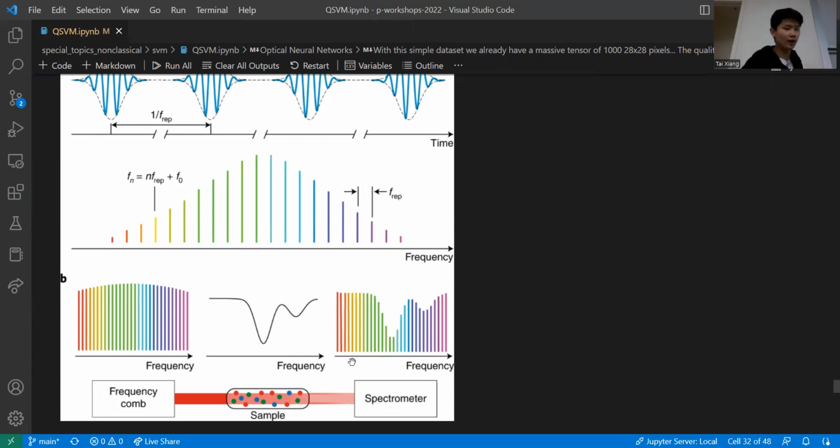So this is a pretty convenient way for us to generate those sort of initial vectors and arrays that we talked about earlier. Instead of having to, for instance, modulate an LED or an array of LEDs or an array of lasers or whatnot to change them into values that we want to encode into vectors and multiply with, we can just use this big frequency comb, send out a wide array of signals, and then just manipulate those through some sort of filter that acts on different wavelengths of light to get them to the desired output we want. So that's a really nice way to do a lot of efficient operations that generate really big matrices when it comes to optics.